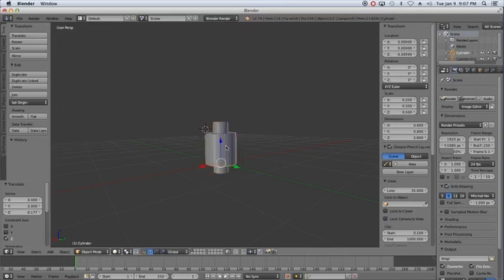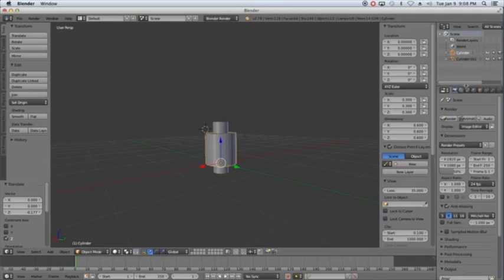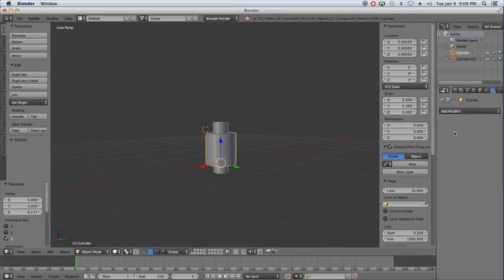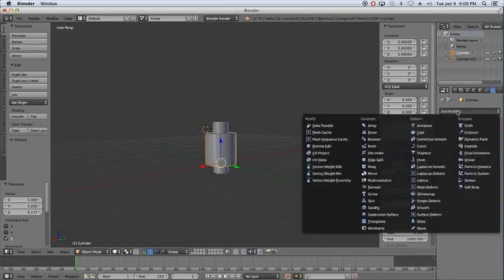I'm going to leave it selected, and I'm going to actually punch a hole in it the size of this cylinder. Now up here in the top right, you've got all of your objects that are currently active. So that's that cylinder. If I wanted, I could click on that one and it gives me that one. And I'm going to leave this outside one selected. And in this little toolbar here, you'll see a little wrench. You click on the wrench, and that's a modifier. So I'm going to use this Add Modifier menu and come over here to Boolean.